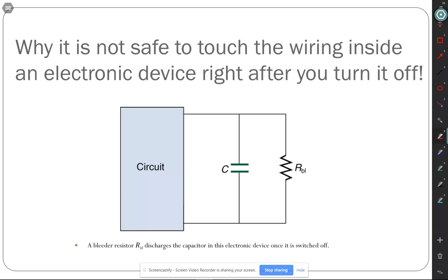So there's a number of ways electricity can damage you. In all cases, it's the current that matters. But of course, our bodies have resistance. And so there's a relationship between current and voltage. So if it's DC, direct current, then the calculations are pretty simple. You're just going to take the voltage divided by the resistance across your body, and that gives you what the current's going to be. The resistance of your body comes primarily at your skin. If you cut inside your body, the resistance is very, very low. But your skin has a resistance that's in the order of tens to hundreds of kiloohms, which limits then how much current you're going to have.